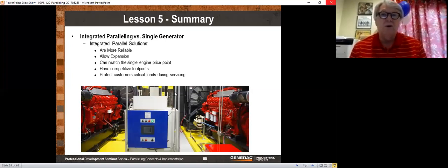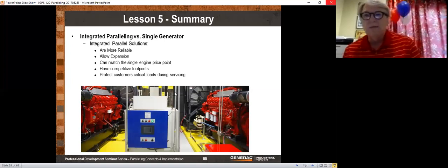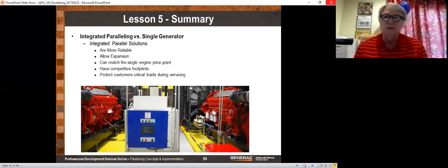And I'm not saying you can't do that, you certainly can. But if you feel like the system has to start and stop automatically when no one's there, then you're going to have to take your 2-wire starts from the transfer switches and so on and figure out a way to wire them into the portable generator. And of course, all this creates a little bit more complication. But other than that, what you're doing really sounds like the right way to go.